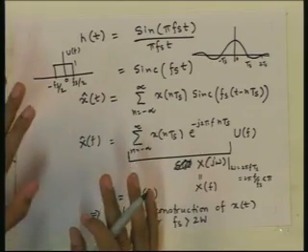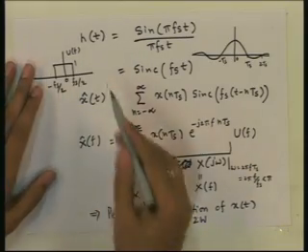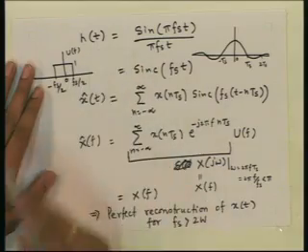We also saw how in time domain why Nyquist rate is necessary for recovery of the original signal, and if the sampling rate is greater than Nyquist rate, we have also seen how to get the original signal back from the sample signal. We need to take this impulse response and pass the delta train obtained from the original sample signal through the filter with this impulse response.